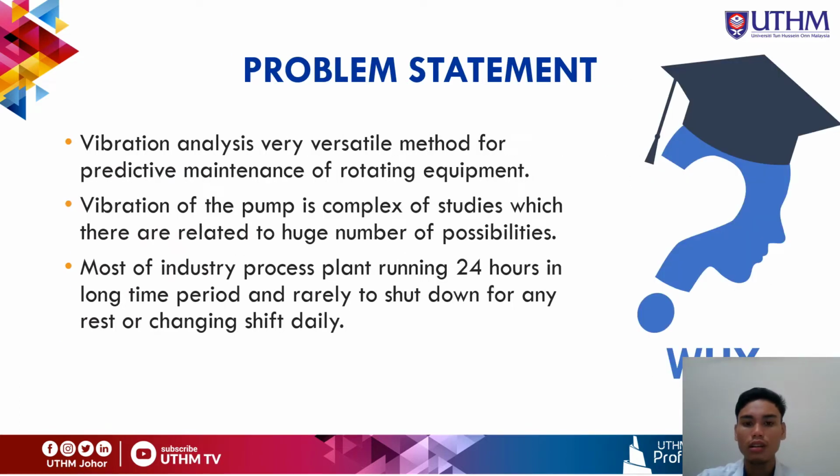The second point is the problem statement. Why did I choose vibration analysis? Vibration analysis is a very versatile method for predictive maintenance of rotating equipment. The portability to measure the vibration and the robust technology can enhance the detection of faults in the pump. The vibration of the pump is a complex study which is related to a huge number of possibilities. We can learn that a mixture of a few faults or a single fault in a pump can be traced by the vibration analysis method.